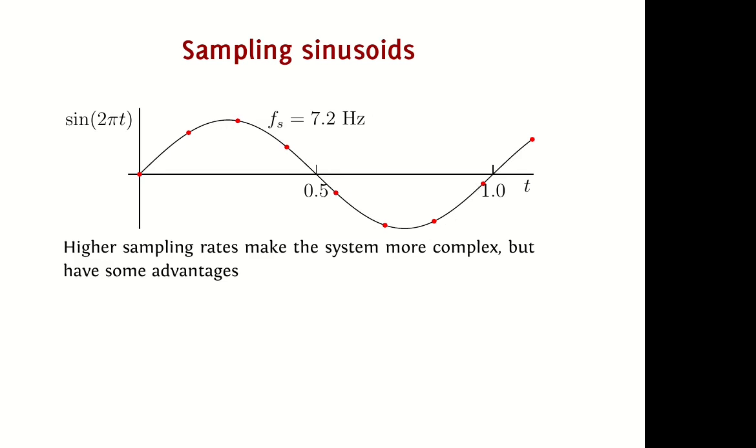Now, it's not always a good idea to sample at a higher rate, but in several situations, system design becomes much easier because representing more samples of the signal may allow you to perform processing easier. Now, these are details which are implementation specific, but remember this comes at a cost because sometimes you're going to perform an analog to digital conversion, and this analog to digital conversion is actually a costly operation, especially when you perform at high speeds.